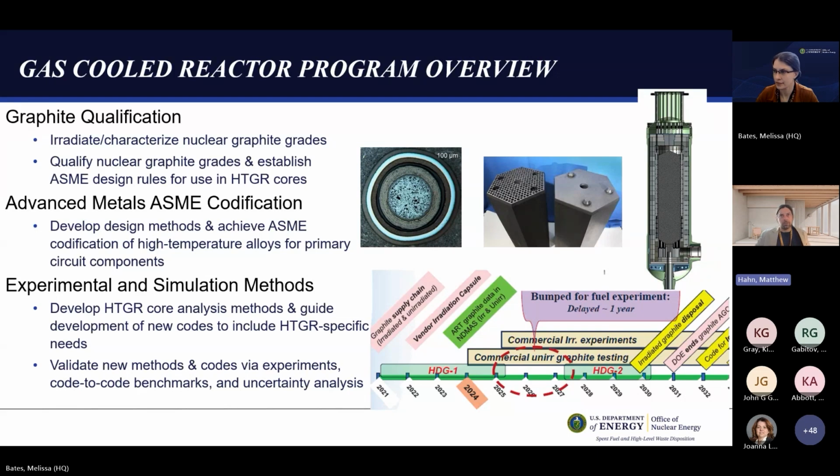High-temperature gas-cooled reactors most often use helium coolant, triso-coated particle fuel, and a graphite core structure, which serves as the neutron moderator. Operating temperatures in the range of 750 degrees C or even higher enable high efficiency for electrical generation, and even more importantly, the coupling of nuclear process heat with industrial applications.